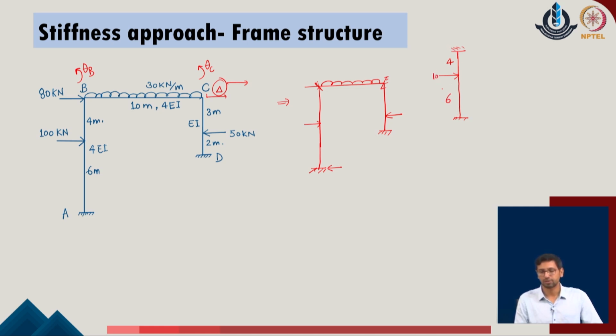Now, one can go back to the same discussions which we did in the standard force method, that corresponding to a fixed ended support or the fixed ended beam, if there is a concentrated load active at any point of the given system, we can evaluate the end moments of the given system for these cases. So, using this idea, we evaluate the end moments of the given problem.